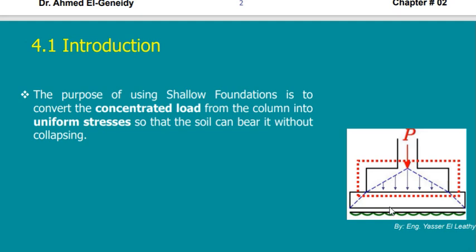The other thing, instead of putting my important foundation directly on the ground, where it would be contaminated by the ground, and some of the ground would go inside the foundation, I have to put something as a barrier between my important foundation and the ground below. So in all cases I will have to put, say, 10 centimeters of plain concrete on the ground to work in a clean environment. So if I'm going to put at least 10 centimeters, why not add another 20 centimeters or something, so that it would be good enough to work and to be considered in my foundation.